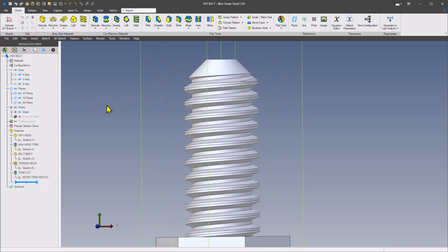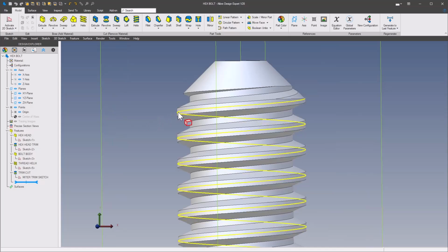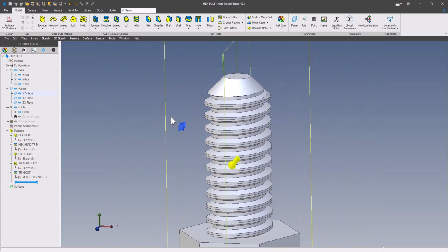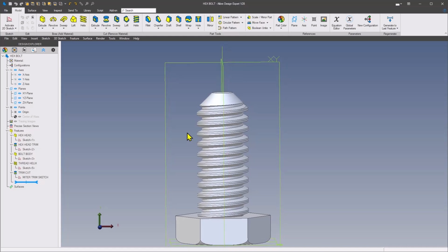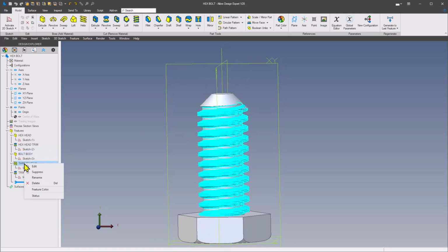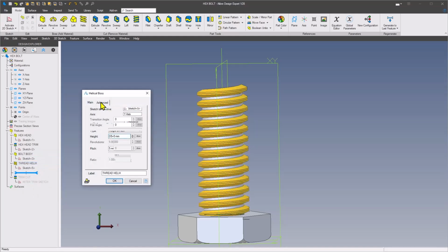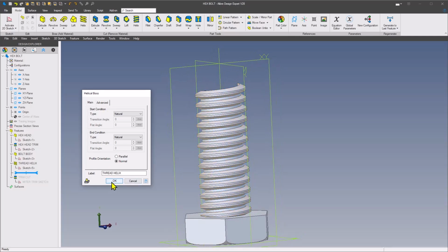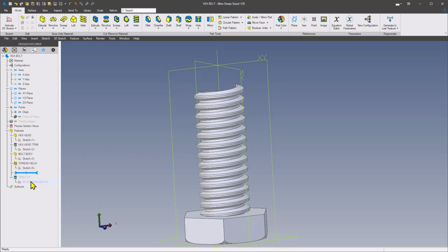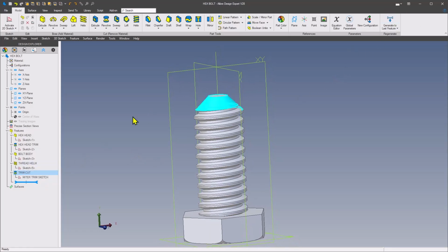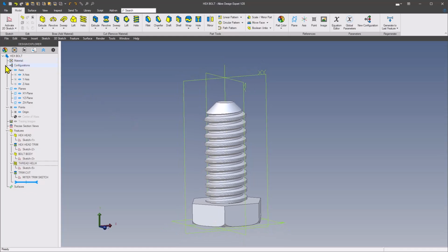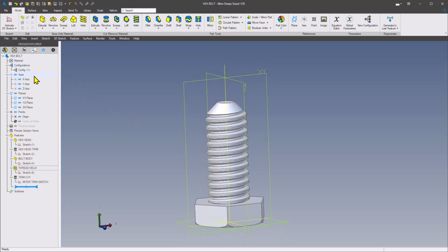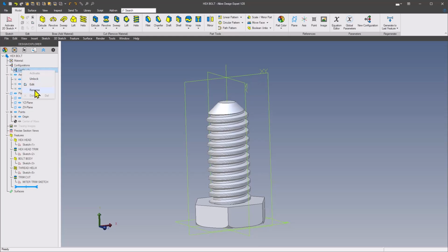And now remember, when we created our hex bolt, we created this with our normal thread. So the thread was turned so that the helix was normal to the path of the helix in our advanced tab. So we have our thread profile as normal. So what we're going to do is use that name normal. In a sense, we're going to create a configuration in here. Go to configs. Let's rename our config 1 here to design size.